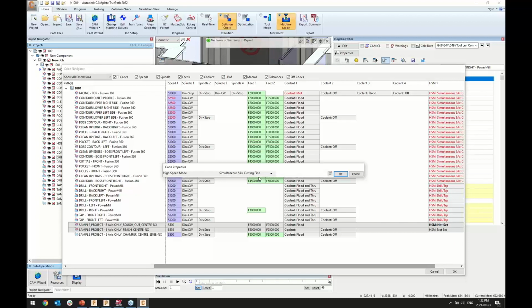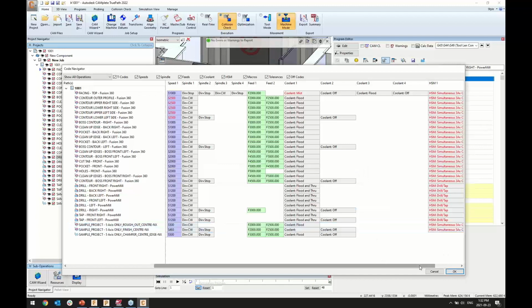On the 5-axis motion, the objectives will be different. It will be a very light cut, very dynamic, but at that point, we really want to focus on the smoothness. We don't want to have any type of jerkiness or strange acceleration in the corner. We really want to focus on a very smooth motion, very accurate, very dynamic, so that we can have the finish that we're wanting to have at the end.